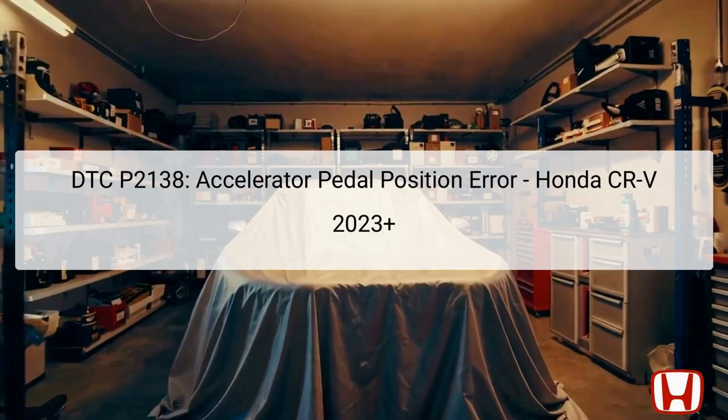The diagnostic trouble code DTC P2138 indicates an issue with the accelerator pedal position APP sensor A and B. This error code is triggered when there is an incorrect voltage correlation between these two sensors. The APP sensors play a critical role by measuring the position of the accelerator pedal, sending this information to the powertrain control module, PCM, to govern engine performance.